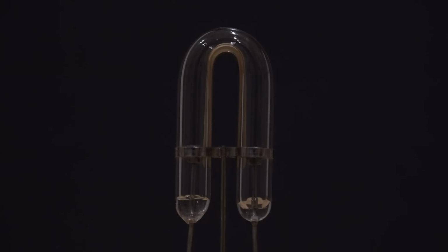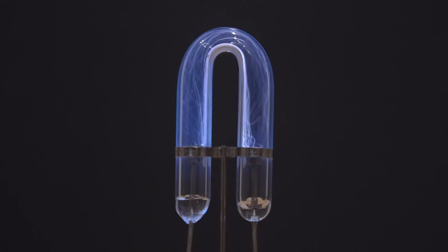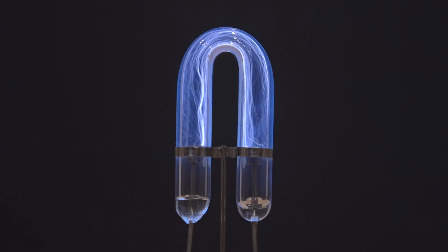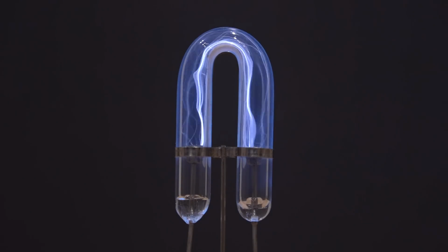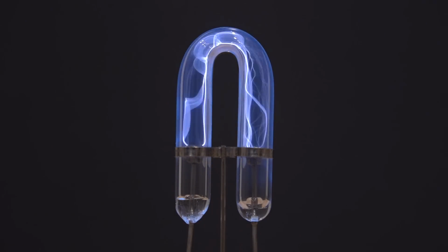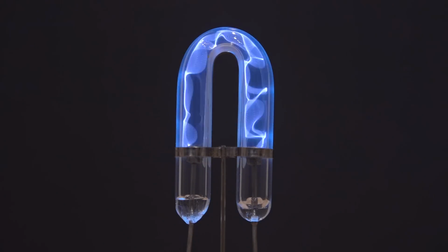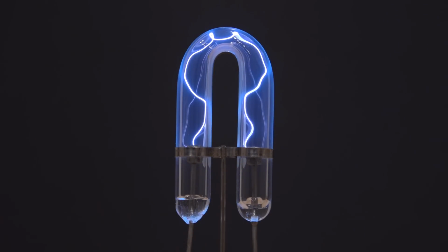So because we have control over the frequency, we can do some strange things using this discharge tube. So I have right now the frequency at 2.5 kilohertz. This is going to be 14,000 volts peak to peak. We turn it on and we can see some activity. Now I'm going to keep increasing the frequency, and look what happens. You have some chaotic discharge in there. And as I increase the frequency, it's going to become more and more well defined. You can see it's still jumping around. I'm at about 10 kilohertz now. Now it's all over the place. As I go to higher and higher frequencies, so here, look at that, around